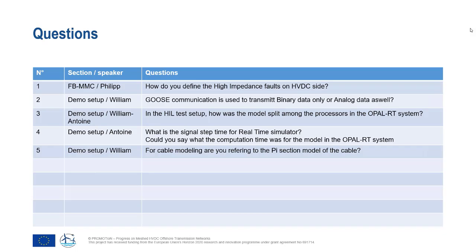Sometimes, if it's not possible, you need to use an element called a decoupling element, which introduces a kind of false physics dynamic to overcome this delay. But it's still a bit messy to do, because you introduce a false dynamic, so you can really destabilize the system. I hope it answered the question.